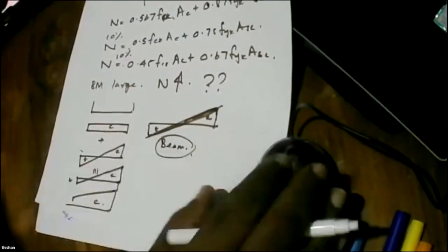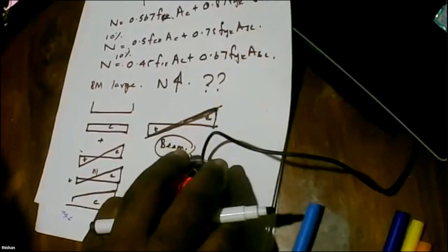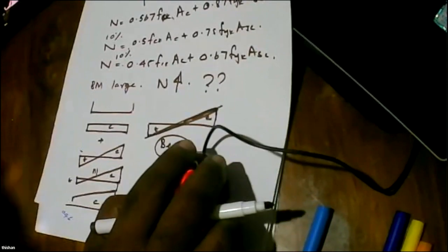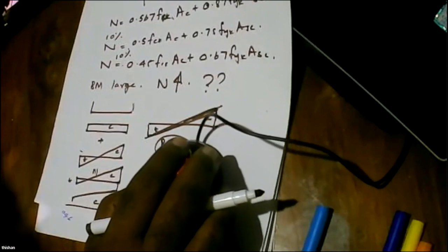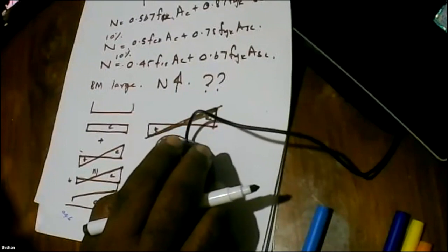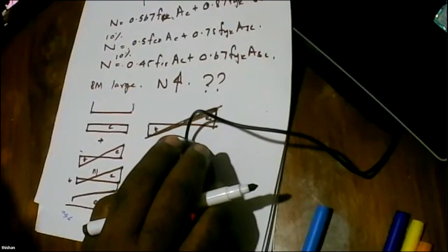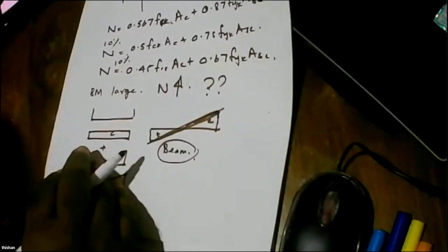So only a little axial load. So now it's more like a beam. So beam behavior is captured by this part of the chart. Column behavior is more axial, so it is captured by this part of the chart. So here the column tends to have a lot of compression and some bending. And again we have to see why we get more compression and less bending.